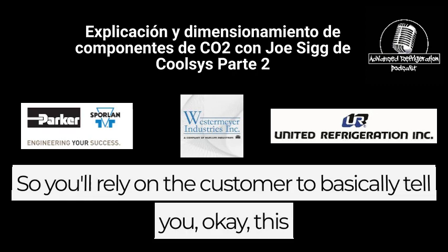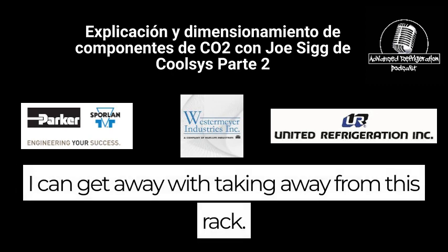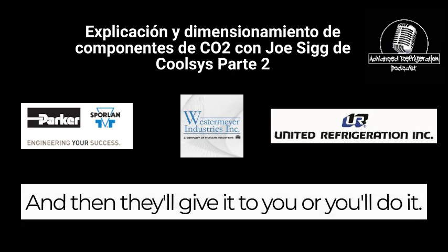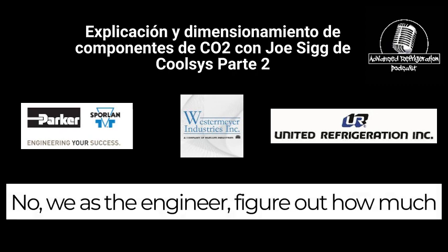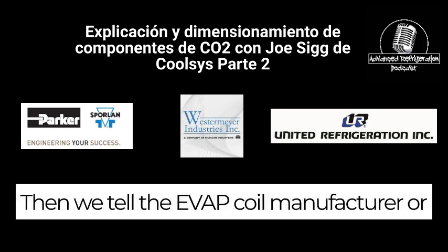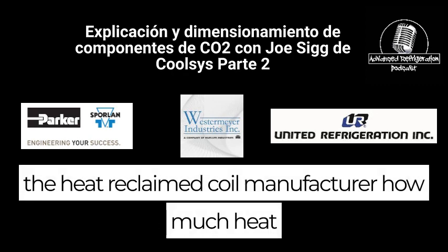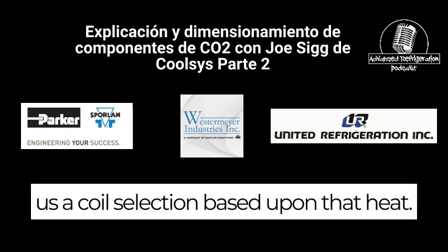Oh, so you'll rely on the customer to tell you how much heat they want to take away from this rack? No, so we as the engineer figure out how much heat we can get out of the CO2 system. Then we tell the evap coil manufacturer or the heat reclaim coil manufacturer how much heat we have to offer, and they give us a coil selection based upon that heat.